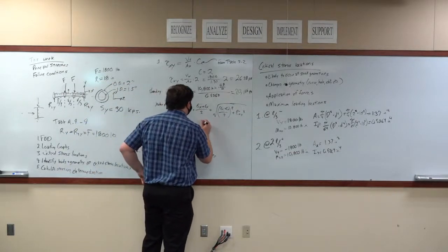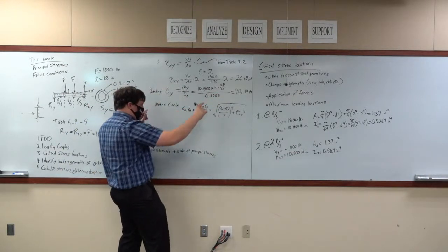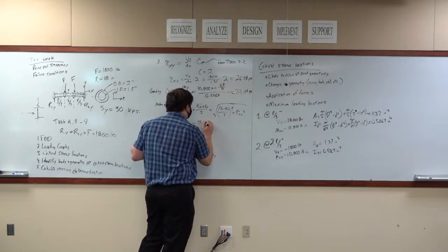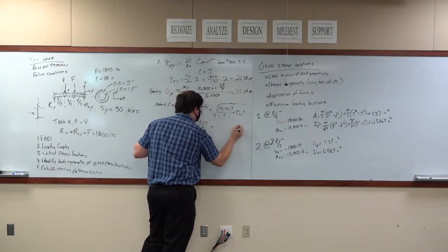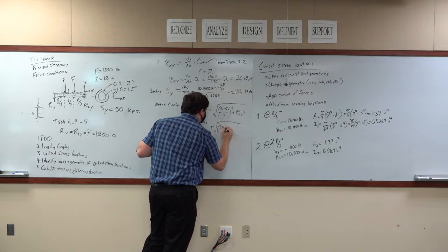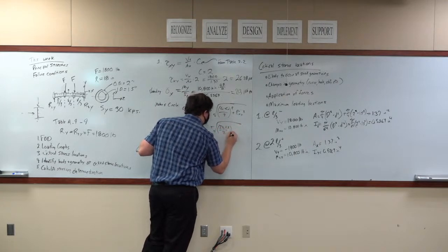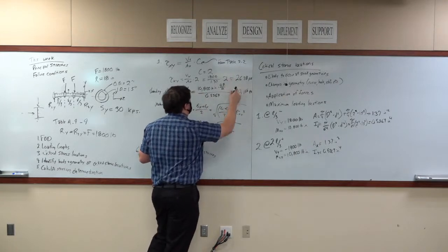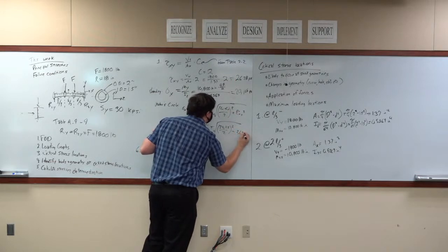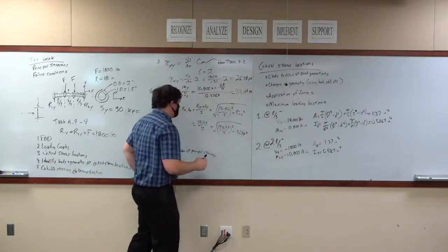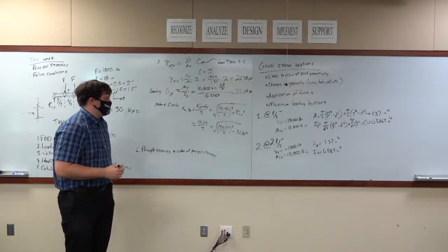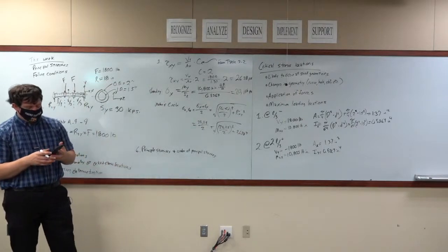So this is equal to sigma x, which is caused by bending, 20,115 over 2 plus or minus the square root of 20,115 over 2 squared plus 2,628 squared. Okay? Sigma A and sigma B come out to be...